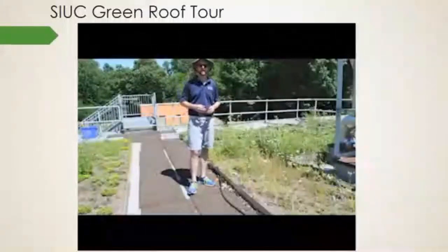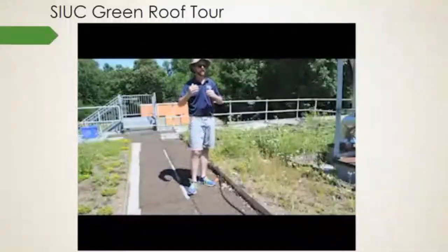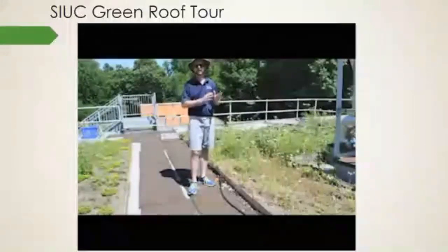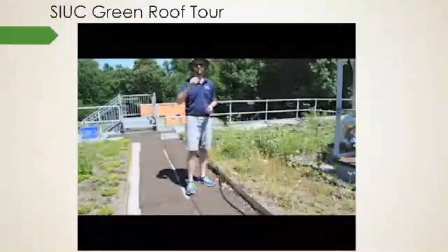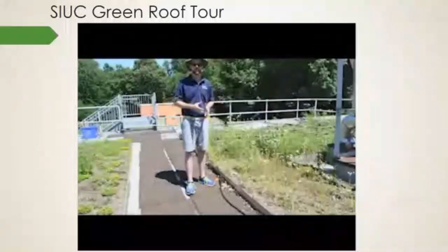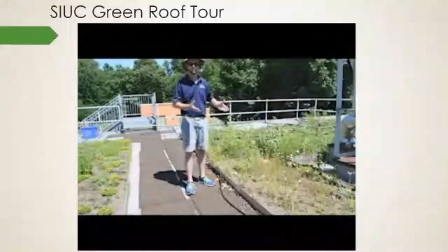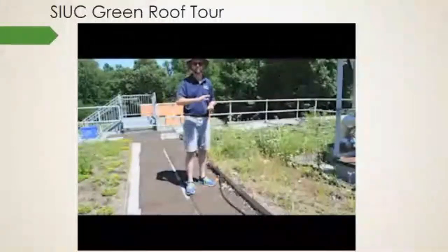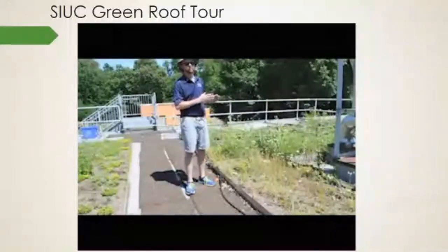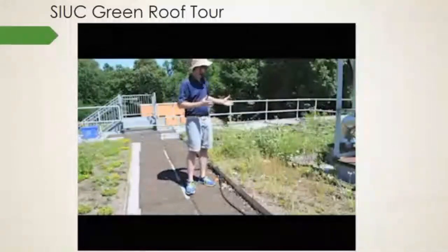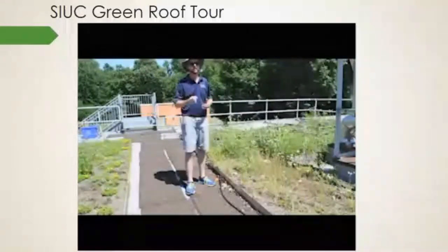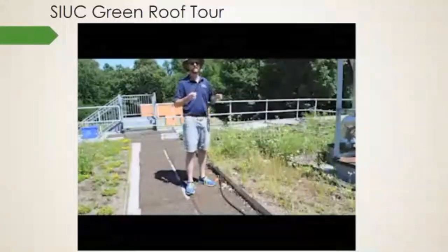And so what we're looking at here is how quick compost breaks down in this green roof medium. That's an important question, because we need to make sure that we're not overloading the medium with more nutrients than it can handle, and that we're not increasing the weight over time. So the previous thought was that maybe compost, cow manure, something like that, is going to break down each year. It's just going to burn up really quick, but that isn't always the case.